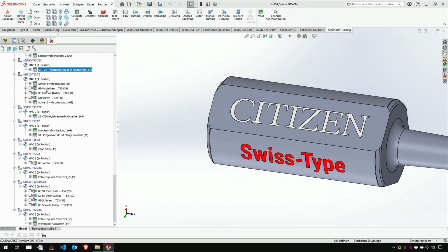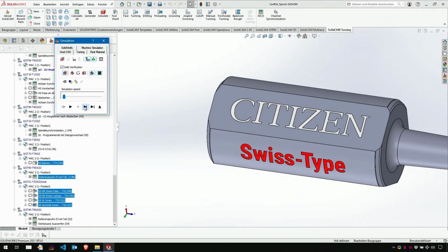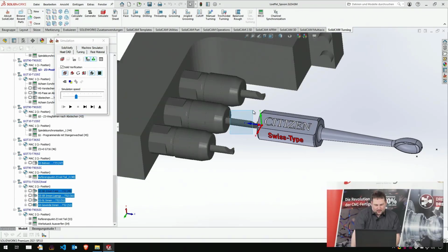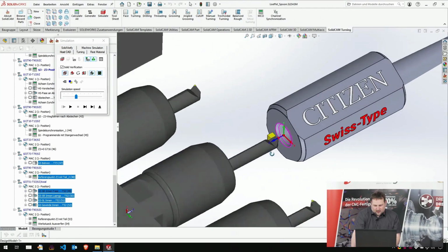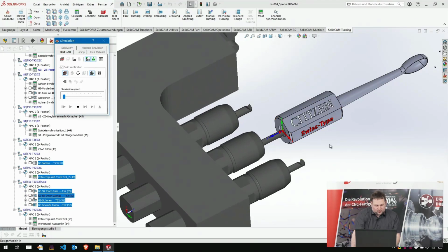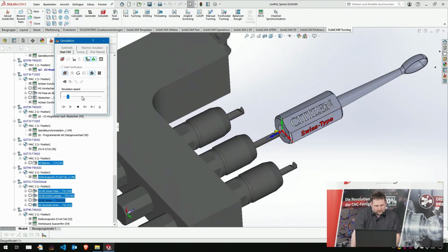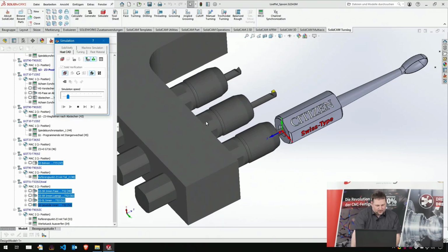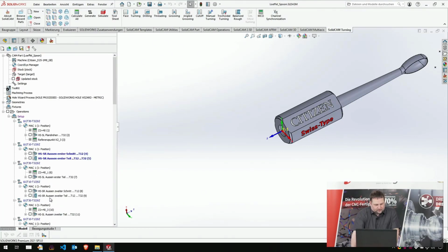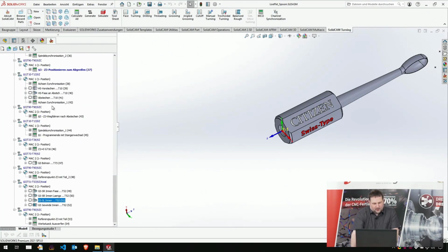Yeah, then we had our cutoff here, and also on the back spindle some small operations. If you simulate this here, just drilling, and then with the ISCAR Pico tools, a little bit of turning and then threading. Yeah, and after we had programmed the whole part, we can go into our channel synchronization here.